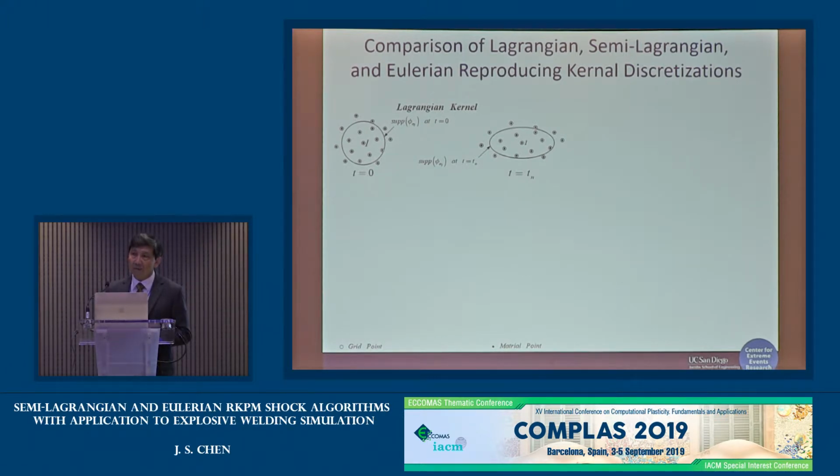So basically what you do is you construct a set of approximations for all the nodes, and then all you do at the later time is just do a mapping through the deformation gradient, right? So this is pretty obvious, and all you have to do is construct a set of approximations at the beginning. And one can formulate the conservation laws, the Galerkin equations, by either total Lagrangian formulation where everything maps back to the undeformed configuration, or updated Lagrangian, and they are equivalent anyway mathematically. But the whole point is just the mapping of the approximations, right?